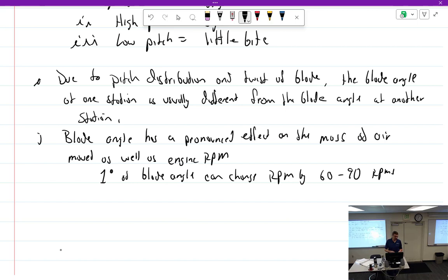Because at a low altitude, you have thick air, so the engine's happy, but the blade's got thick air, so it's fighting harder. You go up to thin air, the engine's not happy, but the blade's got thin air, so that equals out. So it's almost the same across the board. So that's called a static RPM check.